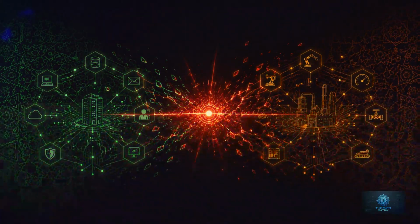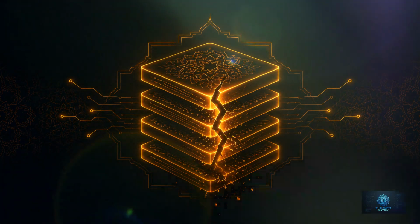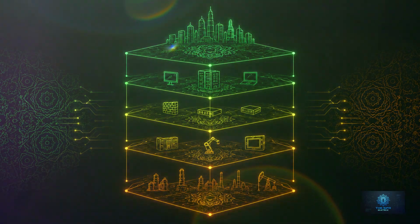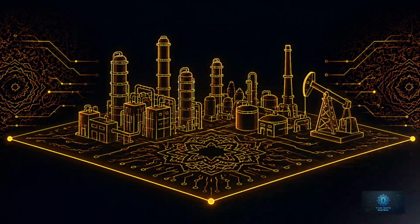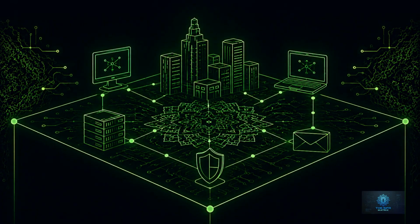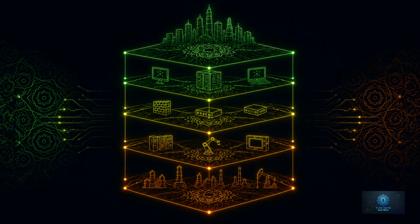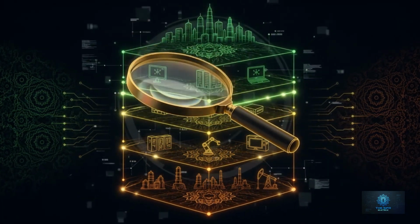Today, we're going deep on the framework meant to prevent exactly that, and why, in practice, it fails more often than you'd think. If you're new here, quick recap. The Purdue Model is a reference framework for structuring industrial networks in layers, from the physical equipment at the bottom, up through controllers, supervisory systems, site operations, and finally, the corporate IT network at the top. The core idea is simple. Keep each layer separated, so a compromise in one doesn't automatically become a compromise of everything.